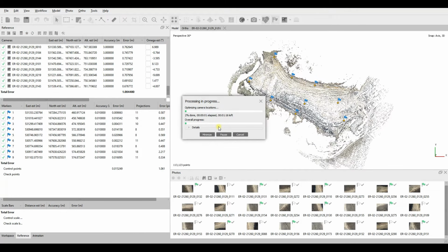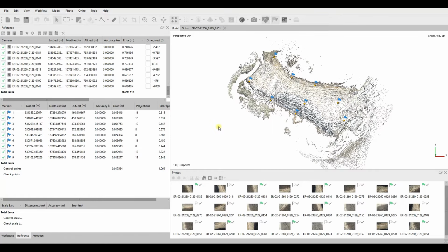You then want to not try to just reduce the error value of those markers down to 0. You want to be cognizant of the fact that there could be mistakes in your GCPs. The land surveyor could have made a mistake in his calculations or in his observations.